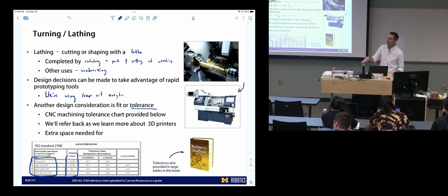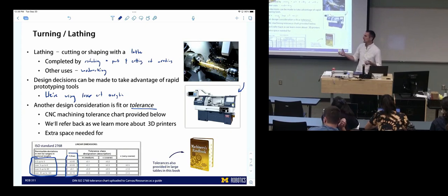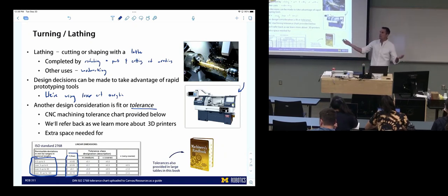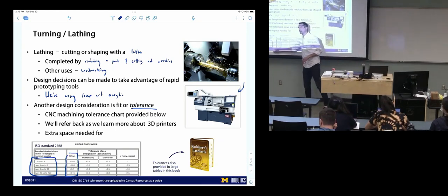But we never use, and I would generally recommend never using, a press fit or an interference fit, because we don't really ever do anything that requires that. You have to assemble it with a heated press or something to make that work. So we use what would be, generally in the machining world, pretty loose tolerances. Locational clearance, or sometimes called transition sliding fits. And so these classes pertain to those types of fits.